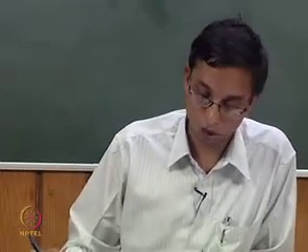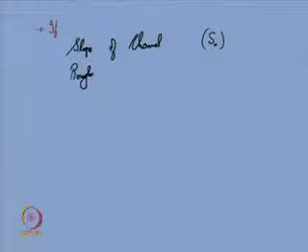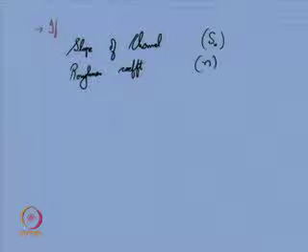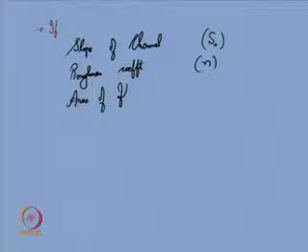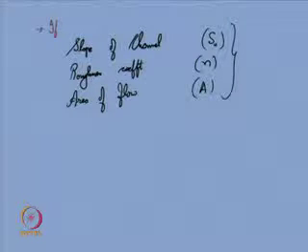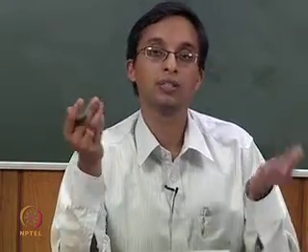Now, what we want to suggest is that if the slope of channel, that is S 0, roughness coefficient, and area of flow, if these three are already given to you, or already determined through other processes, now the next purpose for you is to find the dimensions that follow the efficiency criteria.